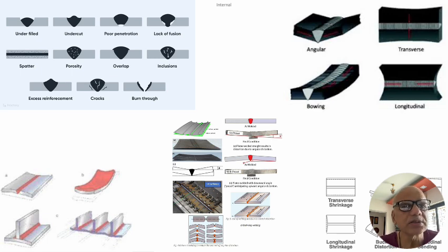And the remedial action is probably something we know: either we break the setup and try to correct it, but if that is not possible, and if we have anticipated earlier, we can give some taper to minimize the mismatch, or we try to do some wedging and excessive fixturing so that whatever mismatch or other setup defects there are, they will not aggravate further, as there will be welding shrinkage or welding distortions.